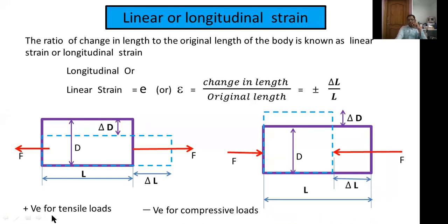Because in this case the length of the component may increase, and in this case the length of the component may decrease. That's why for compressive loads you have to consider the minus sign, and in tensile loads you have to consider the positive sign.